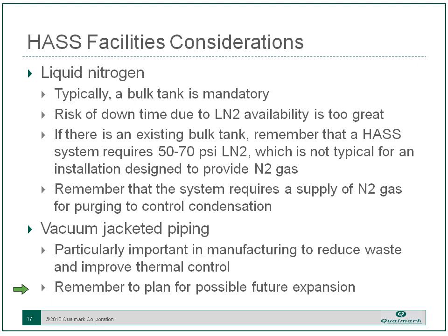If you don't do that, then it is expensive to add on future chambers, because once that vacuum jacketed piping is built, it's in that configuration, and you can't cut it up and modify it in the field. So putting a bayonet fitting at the end of your line can make sense, so that as production goes up or another product comes online, you'll be able to expand that piping without too much trouble.